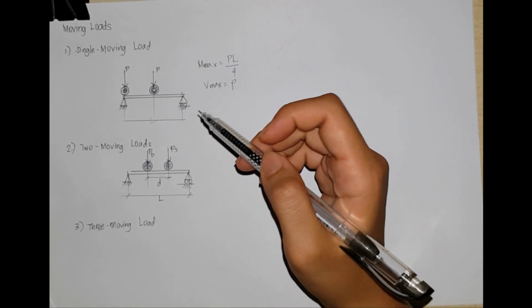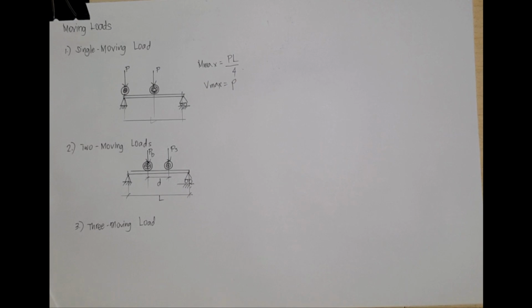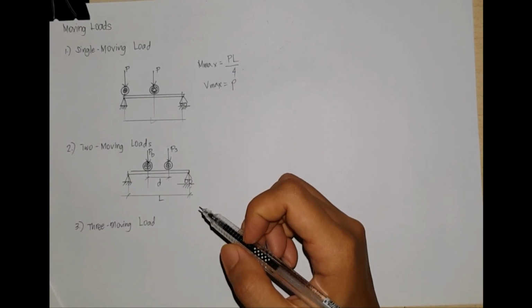And then for two moving loads, the maximum shear occurs at the reaction when the larger load is over that support.